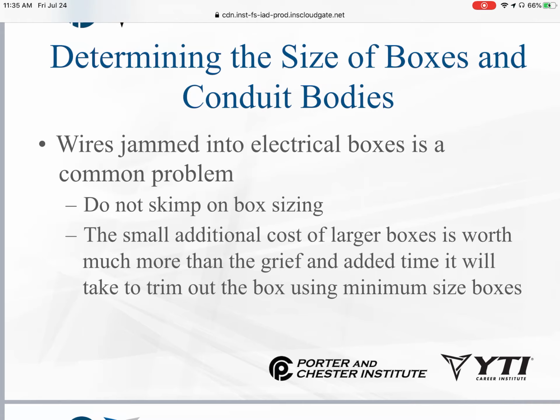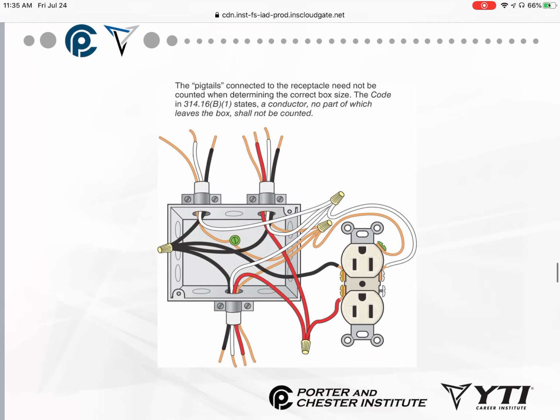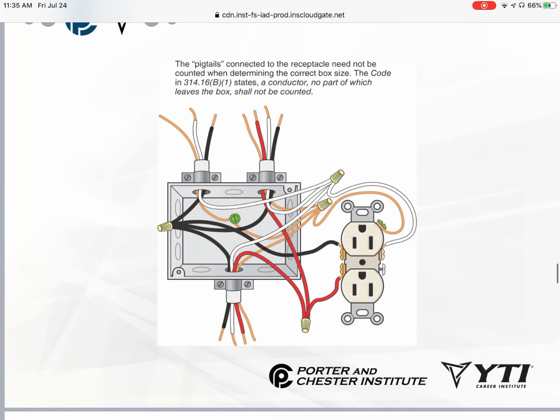You're going to really appreciate that when it's time to put your devices in and so forth. It's worth it to pay the extra price for the larger box in the long run. It's going to cause less problems for troubleshooting, and all that. The only time you're going to go with shallower boxes is out of necessity. You just can't seem to get the bigger box in there. So that's what you want to do.